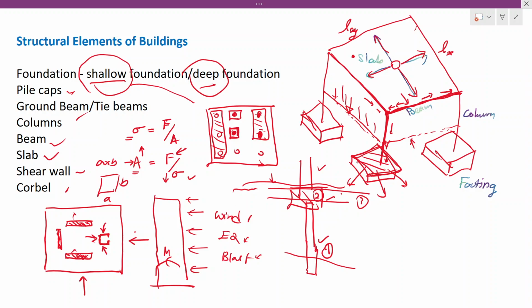Let me briefly explain the function of the lift wall. Now, the shear wall. If you have two walls, something like this, and a lateral load like this, the more effective type is this one, because the other will easily bend. This is a plan view. When you have a wall like this and a lateral load like this, it can easily bend that way. But when you have a wall like this and a load like this, it will be difficult to bend in this direction, though in the other direction it will easily bend. This way it can easily bend, but along the wall it will be difficult.